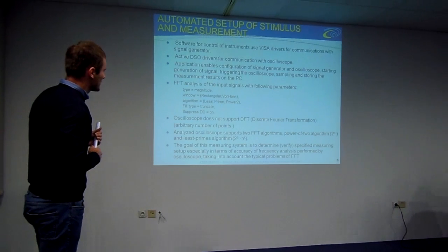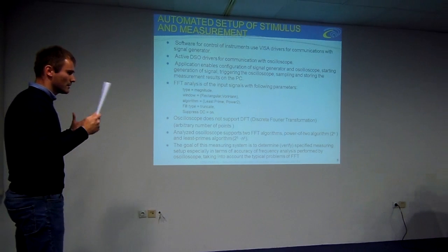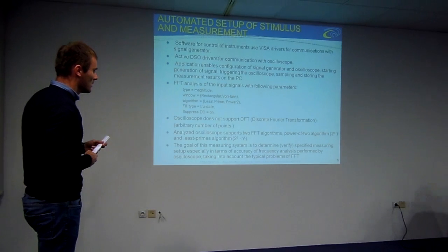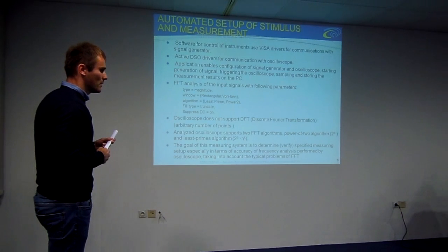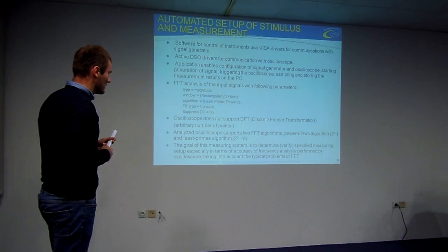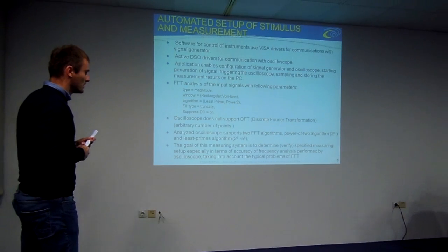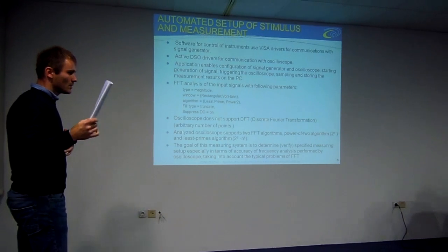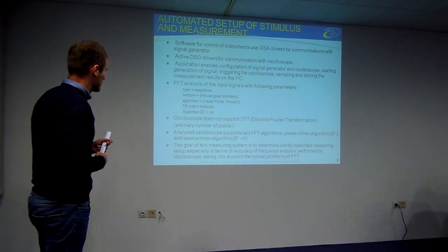The second thing in the automated setup, and an important one, is the measurement of harmonics in the response. If we measure harmonics on the response of the motor, we get some response that is different from the signal we generate.